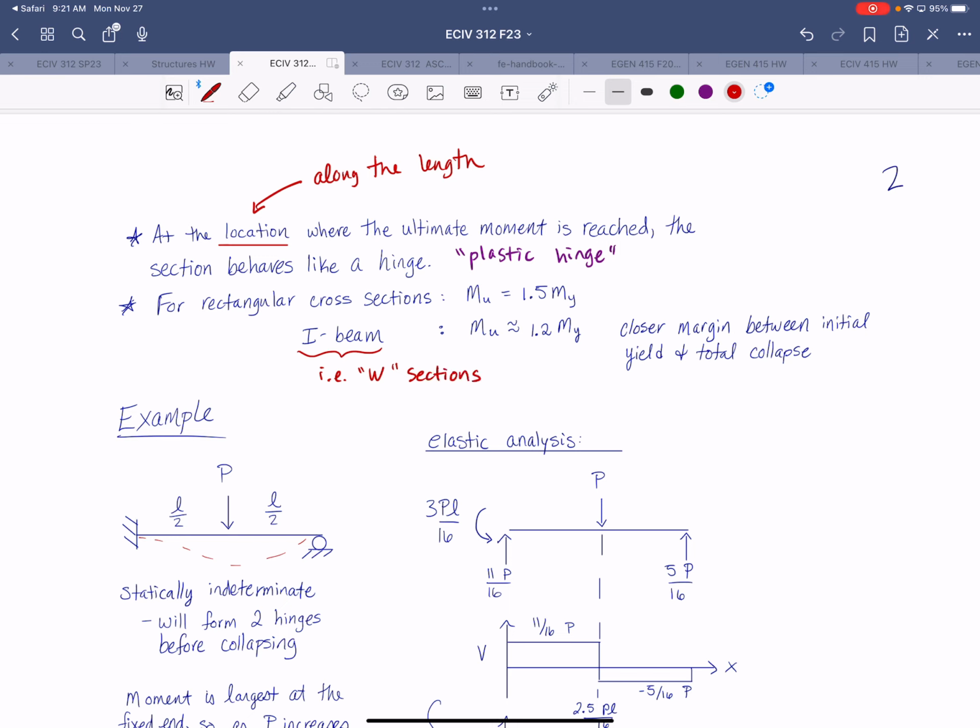So you had a little bit of exposure to working with W section designations in homework 2. So remember, if you have, for example, a W12 by 10, that means it's approximately 12 inches deep and the weight is 10 pounds per linear foot. So remember how that designation works.